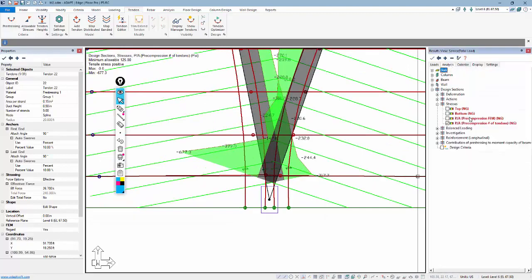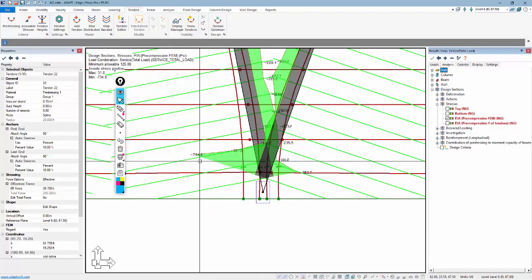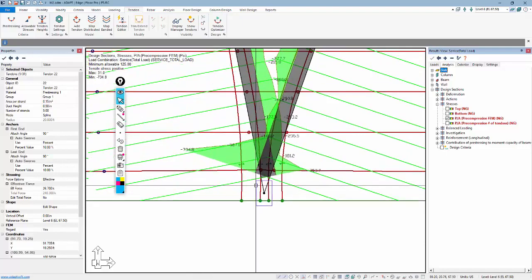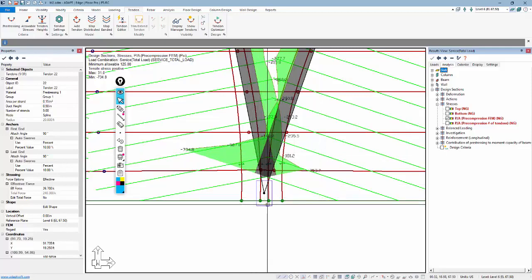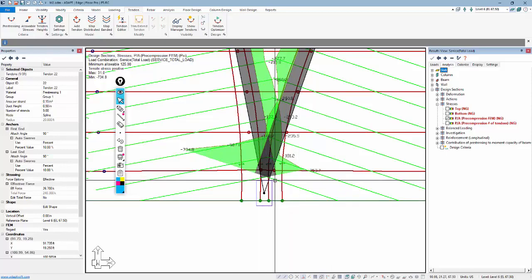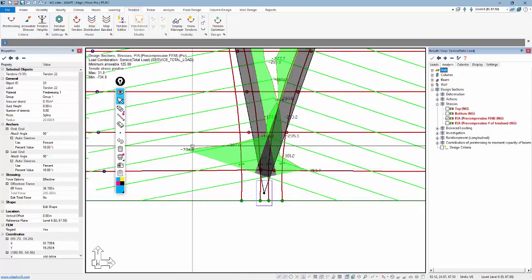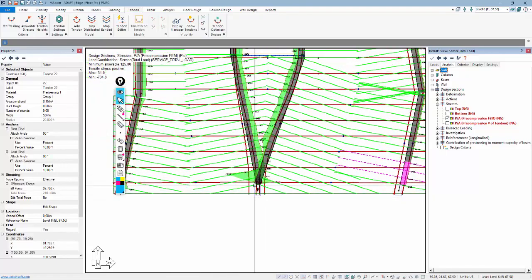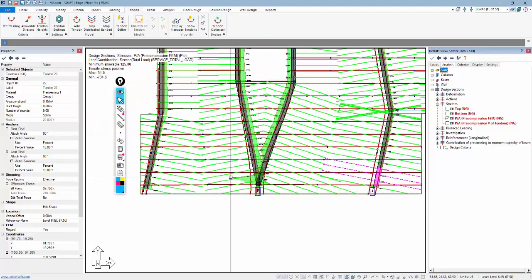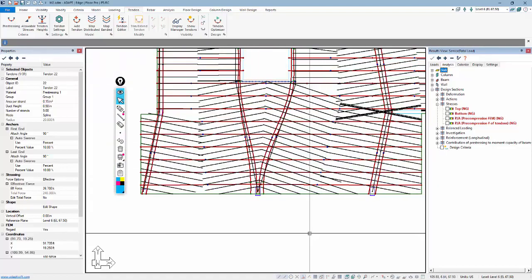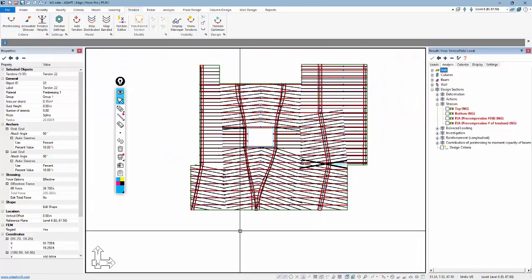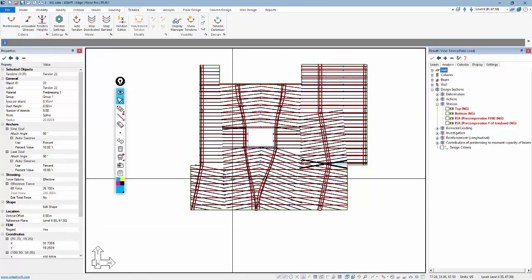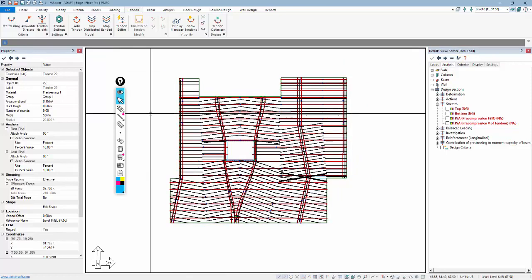Now if we go to the P over A check, that could smooth that out a little bit, or it could increase like it has here. Now we actually have more force, because now some of these tendons over to the left are contributing to the in-plane precompressive stress in that area, and we're really just integrating over that stress here to get this value. So something would have to happen here. This is probably too many tendons that are converging on that one column in this model, and you get that high spike in precompression, or the user just has to make some judgment as to whether that is an acceptable level of precompression in that zone of the slab.